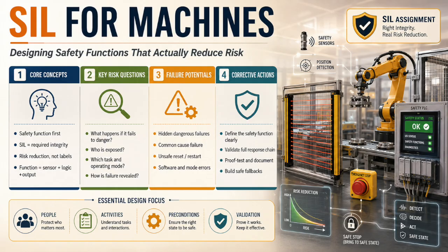That is why software and safety systems must be treated with life cycle discipline. Requirements, design, review, verification, validation, version control, access control, change management, fault testing, documentation, revalidation after modification. If you change the program, you may have changed the safety basis. If you change the speed, tooling, material, layout, guard position, drive, sensor, actuator, or operating procedure, you may have changed the SIL assumption. That is why documentation is not paperwork. Documentation is memory.